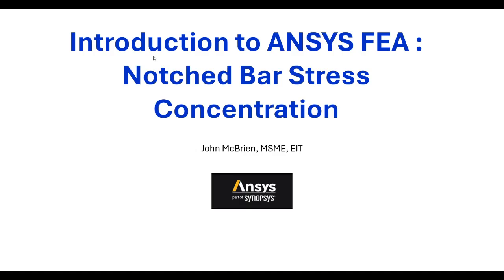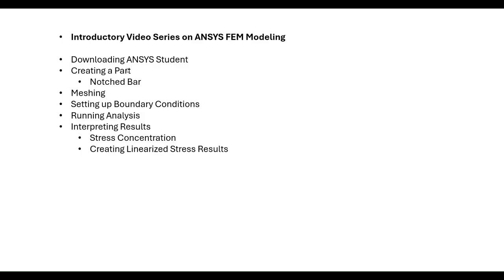All right, welcome everybody. Today we're going to do an introduction to ANSYS FEA with a notch bar, and we'll calculate the stress concentration. So I'll show you briefly where to go to download ANSYS Student, and then we'll create the notch bar, and I'll show you how to mesh it and set up the boundary conditions. We'll run the analysis and then interpret the results.